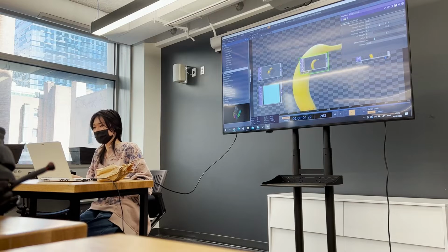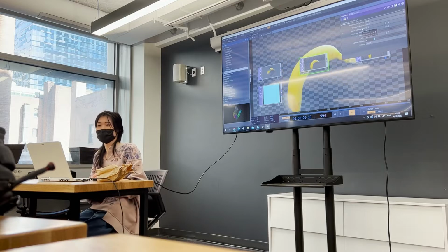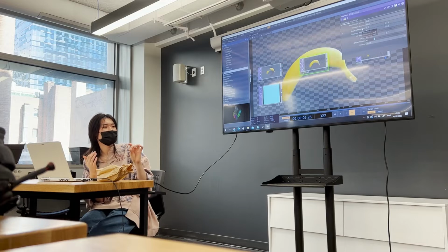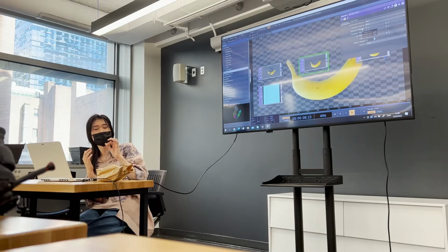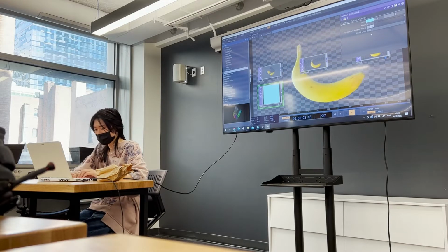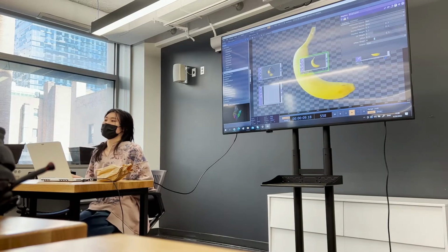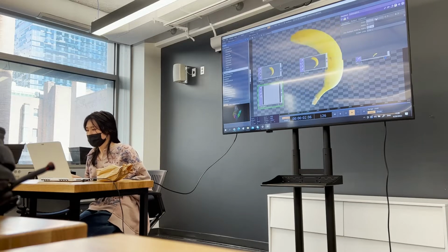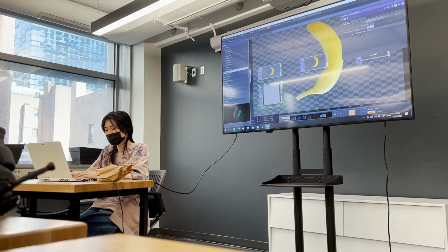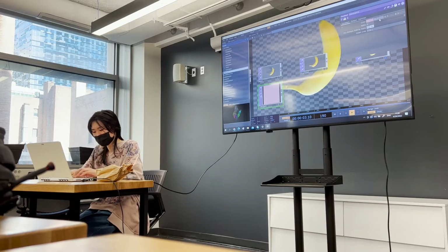Because there's a source midpoint in the displace node that essentially says 0.5 in the RGB value means no displacement at all. So if I change everything in the constant to 0.5, you can see it doesn't do anything. But if you want to move it along the x-axis, we can change the value to like 0.7, and it's going to move to the right, to the left actually. Okay.